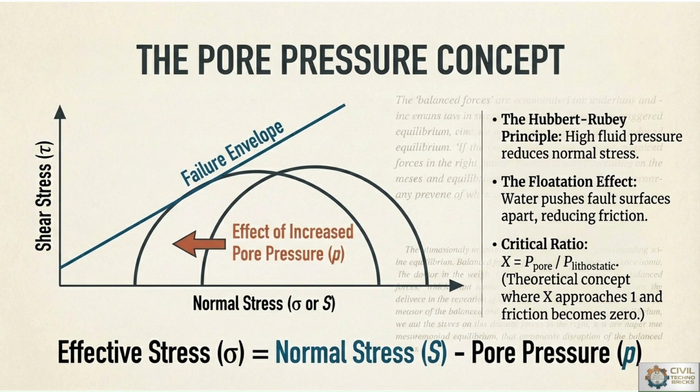An increase in pore water pressure reduces effective stress and weakens the material. High pore pressure can trigger failure in slopes, foundations, fault planes, fault zones, etc. So monitoring the groundwater pressure is most essential for dam safety evaluation.